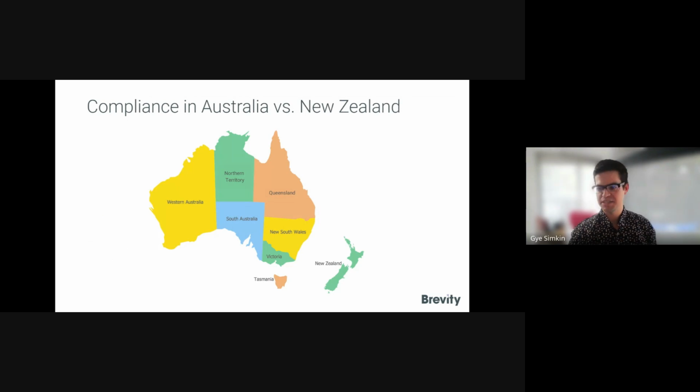So this presentation is talking about the compliance in Australia, and let's talk about how it compares to New Zealand as well. In episode 1, we covered compliance pathways of seismic restraints in New Zealand. In New Zealand, we use the terminology of producer statements, or PS1s, as a means for engineering certification.